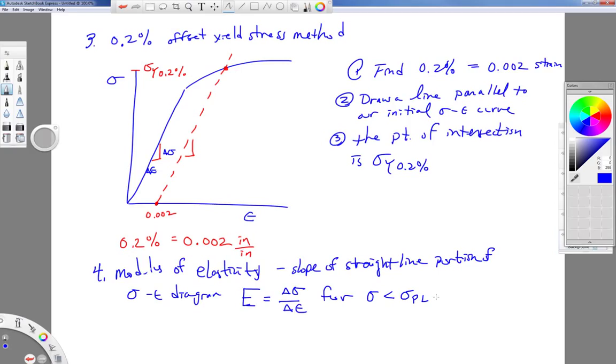The units of the modulus of elasticity are the same as the units of stress because strain is dimensionless. The number for the modulus of elasticity is usually much higher than any number that you would get for stress, however. Because the strains in most engineering materials are very small, stresses may be on the level of KSI or megapascals. Strains might be on the order of 10 to the minus 3 or 10 to the minus 6. So we end up with gigapascals, typically for a unit of modulus of elasticity, or millions of PSI, in MSI, or 10 to the 3 KSI for those units.